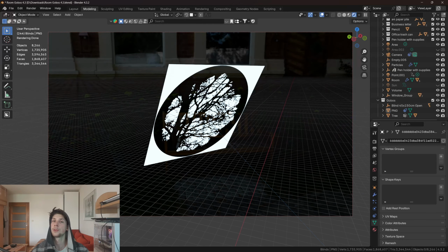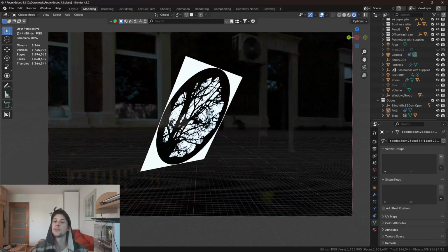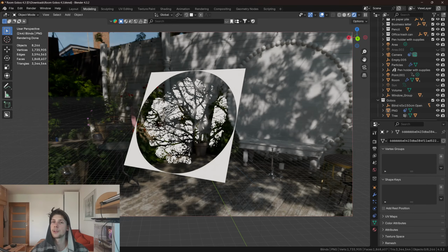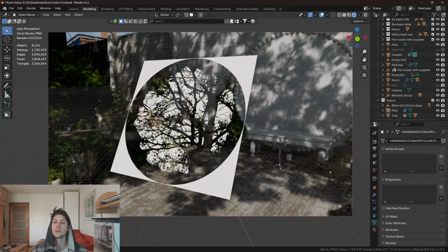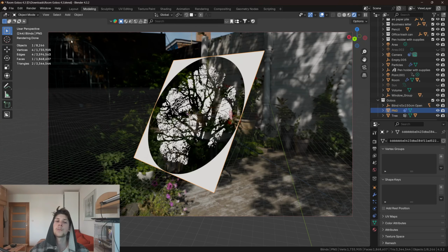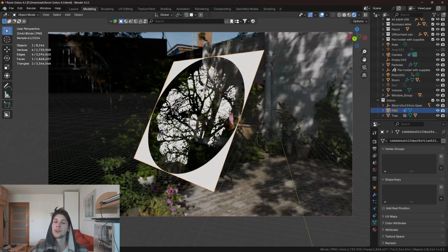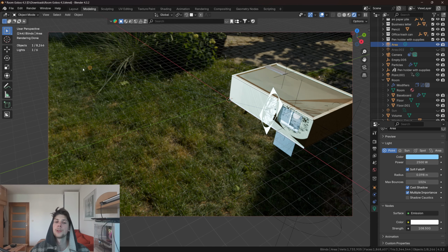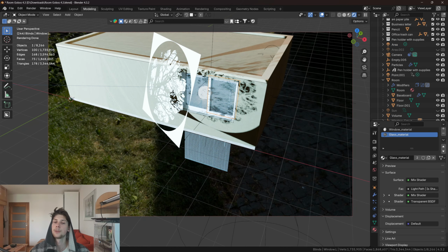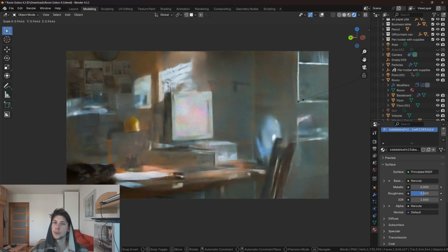Luckily, this can also be achieved with textures. All you need is a two-dimensional plane and a grayscale texture that you can plug into the alpha channel, which will make the black parts transparent, so the light from the light source will only go through the transparent parts. So here we have the light, which is coming through the window into the room, creating that shadow pattern from the image and projecting the image onto the walls.